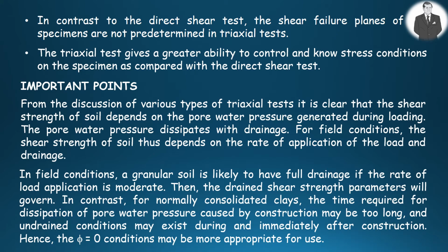On the contrary, for normally consolidated clays, the time needed for dissipation of pore water pressure resulting from construction may be too long. An undrained condition may govern during and immediately after construction. Therefore, the phi = 0 conditions may be more suitable for use.